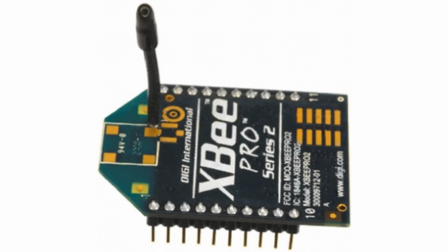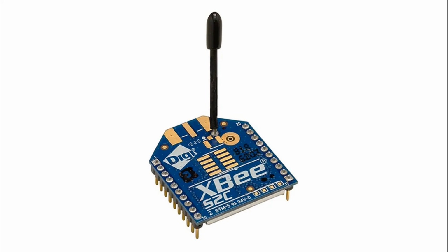1. Low power consumption. Zigbee is designed to consume minimal power, enabling long battery life in devices, often lasting months or even years. It supports sleep modes and low duty cycles, making it ideal for applications where devices are idle most of the time but need to transmit data periodically. 2. Mesh networking support. Zigbee supports a mesh network topology, where each device can relay data to others, creating a robust, self-healing network. This mesh capability extends the communication range by allowing data to hop between nodes, making it suitable for large-scale networks and areas with obstacles.